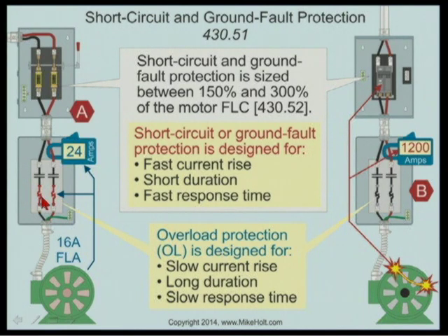These overload devices are designed for slow current rise, probably slow temperature rise, probably more than slow current rise. It would be a slow temperature rise, and it's a current that's going to be long duration, and the device responds slowly. So if I put 24 amps on a 16 amp overload, this baby is not instantaneously opening.